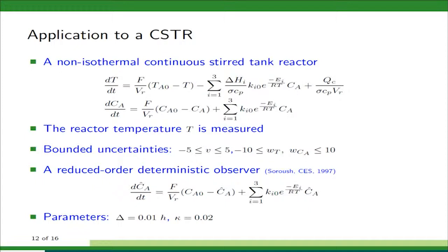We designed a reduced order deterministic observer for the concentration. This observer is actually a copy of the second equation without considering the disturbances. And the design parameter kappa is tuned to be 0.02.